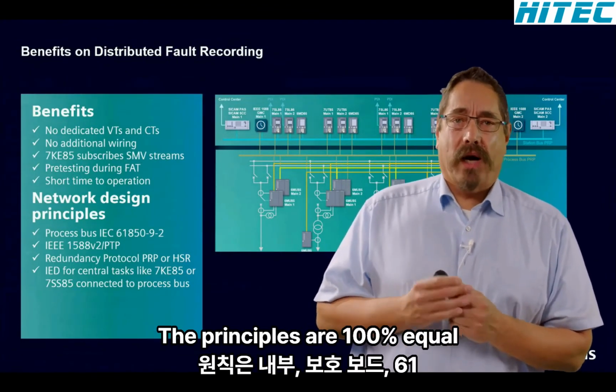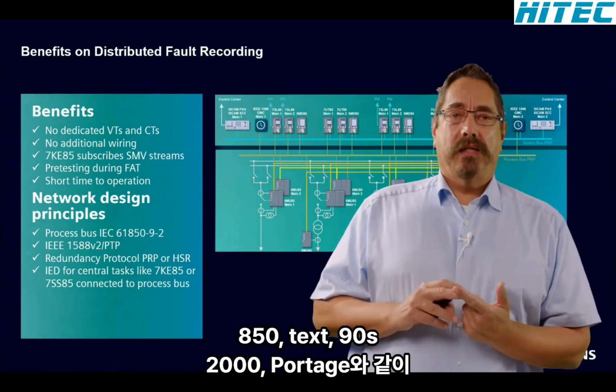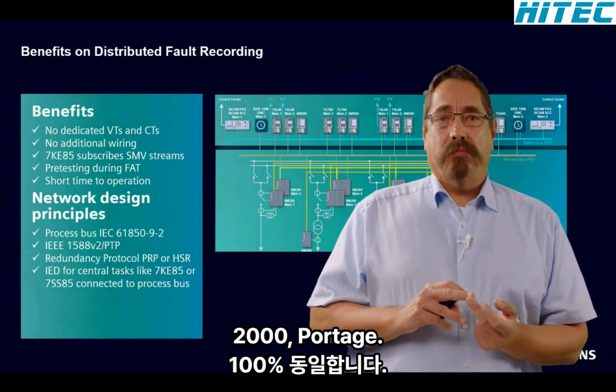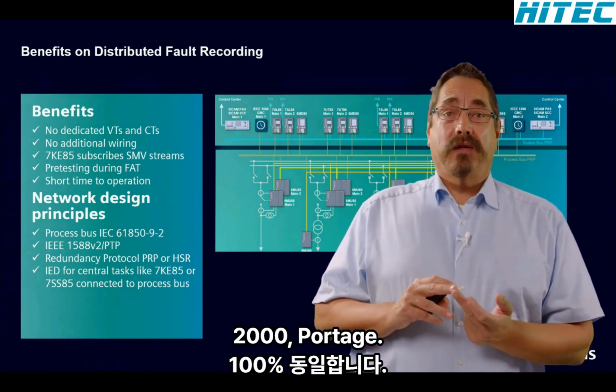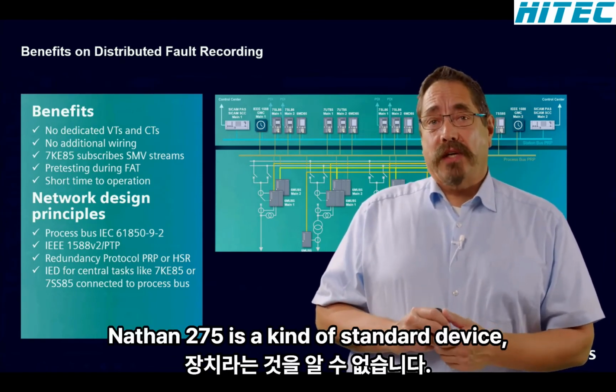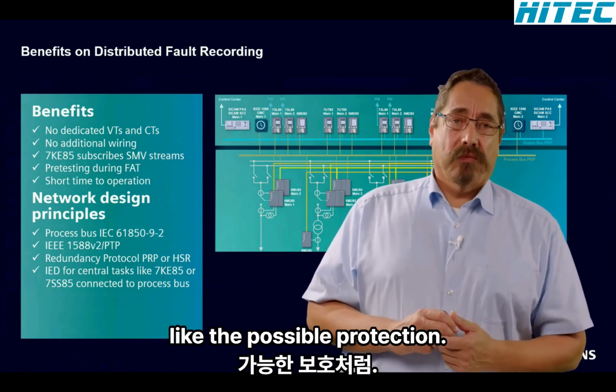The principles are 100% equal, like in the protection world. IEC 61850-9-2, Precision Time Protocol, PTP, and the PRP and HSR redundancy concepts are supported. You can imagine that the 7KE85 is a kind of central device, like the busbar protection.